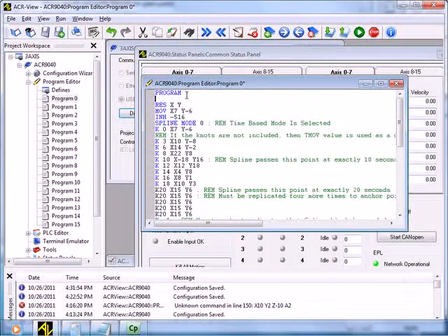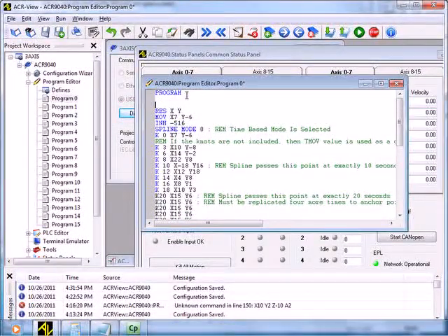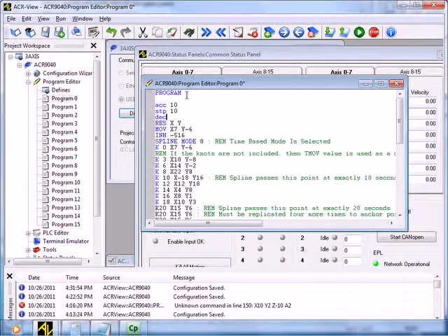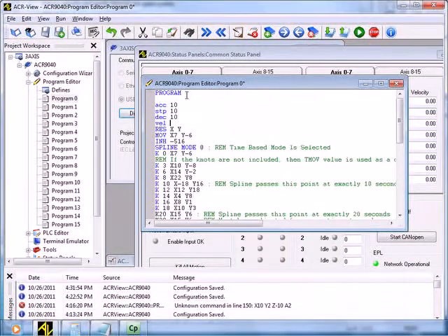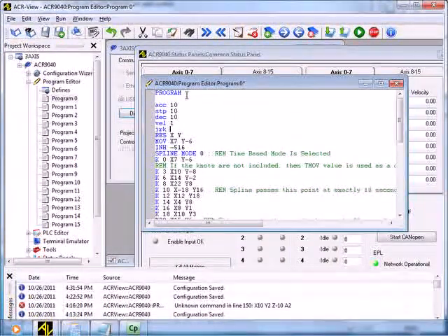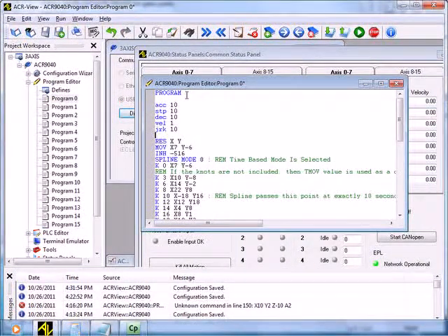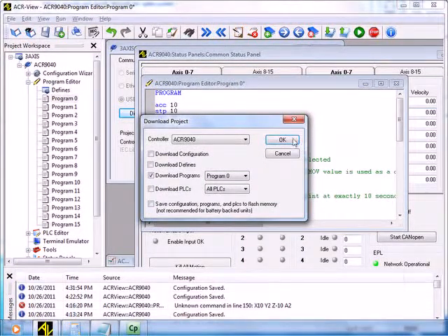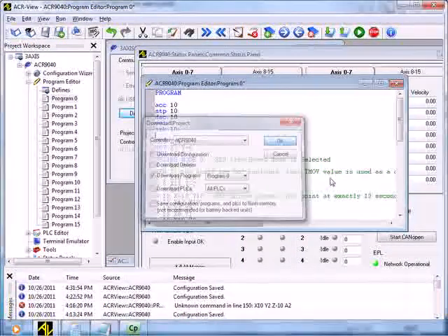And we're going to go to the XY plot, and under the motion tab we have run prog 0. For the sampling, we'll go ahead and set it to PC sampling 50 seconds, press OK. Divisions is 50,000 units per division. Go ahead and click run.